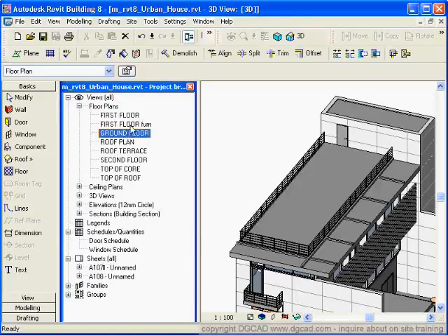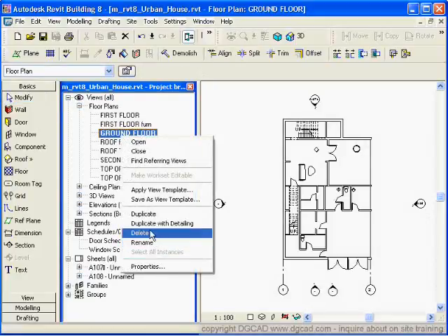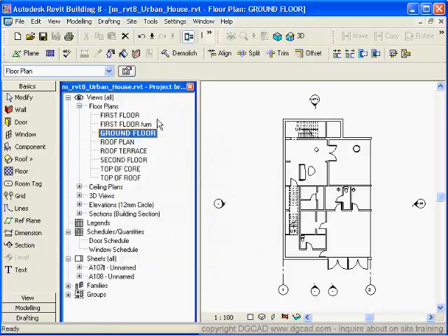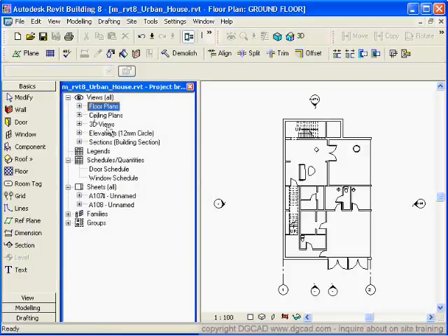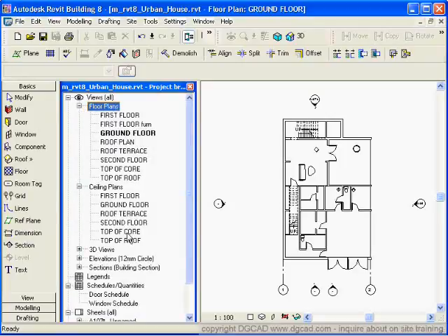to each other. So wherever that name might show up in a drawing list, or however that field gets, if you change it inside of here, or you rename that, or delete it. If you delete it, all the objects will delete from it, and it'll most likely give you a warning. So floor plans are view types. Every time you make a floor plan, it makes a corresponding ceiling plan for you right in there.